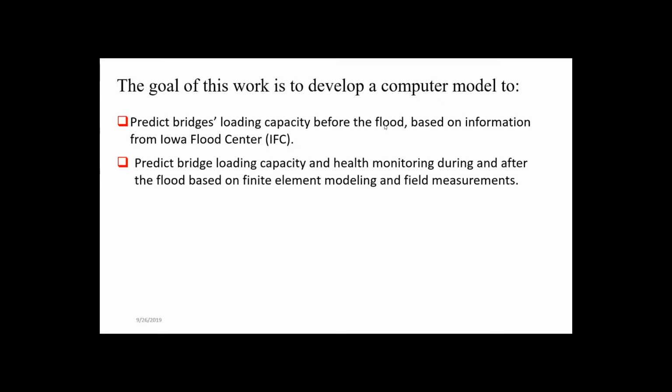Again, as I mentioned, this is before, but during and after the flood, this becomes more challenging, because there are other forces in addition to water, as I showed you in the first slide, like fallen trees and objects. And these will generate forces that we cannot predict, because they are random events. So it will be nice if the computer model could get some measurements from the field. So if you put some sensors on the bridges, they will always give us real-time data on what's going on, and this will enhance the model's capability in predicting more accurate results.